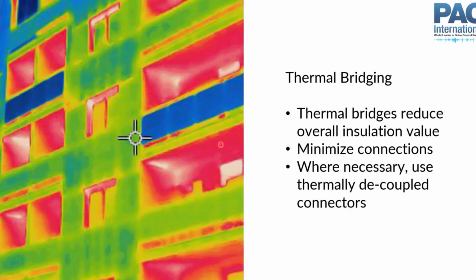So if you've got your building envelope and you're looking for improving the thermal insulation of that building envelope, it's not as simple as just specifying a higher R value insulation to go in your stud cavities, because you have this other transmission path for heat that would be through those connections from the outside of your building envelope to the inside of your building envelope. And usually that's a stud, and that'll transmit more heat. So you can get this sort of cumulative composite insulation value for your assembly.